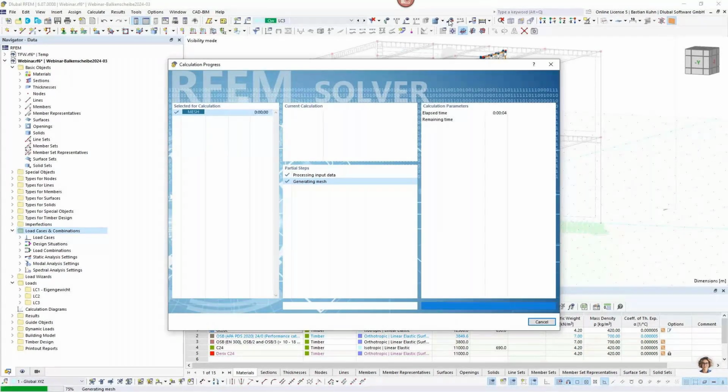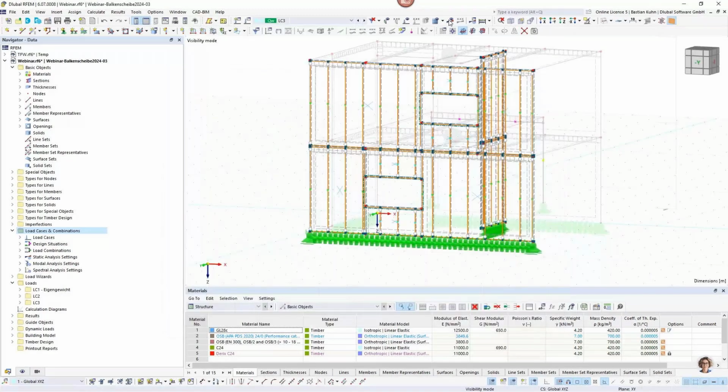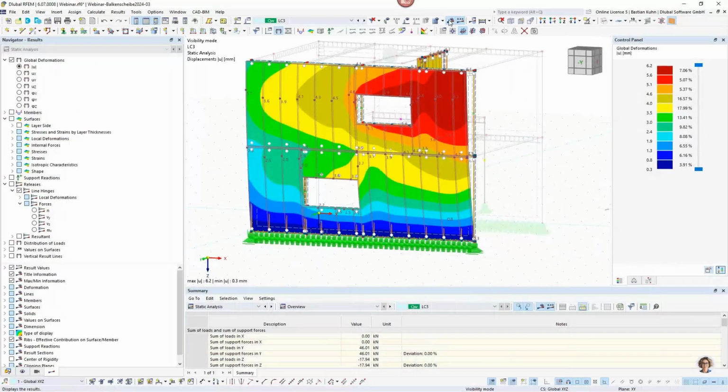Okay, it's not a real small structure, not even a big structure, but I also use the building model inside just to get my masses all around. So masses maybe also a good point. One other advantage of using such a 3D object is that you can use the stiffness of the timber frame wall similar to CLT for every calculation. So also for your dynamic analysis, you can create response vectors and use it for this.